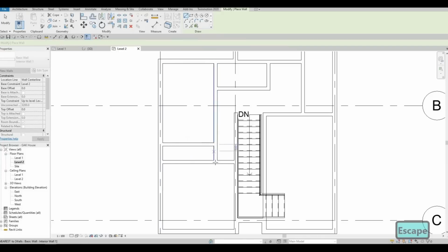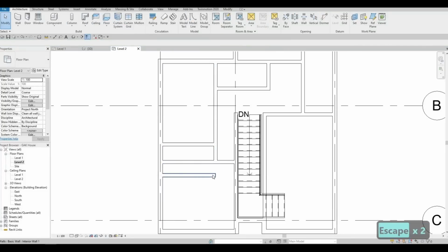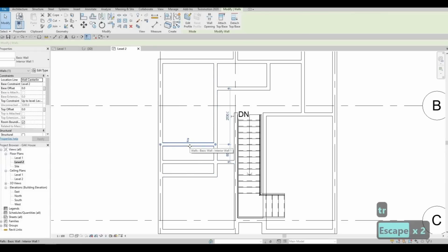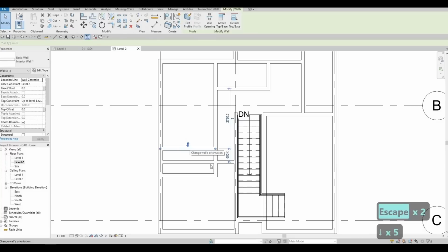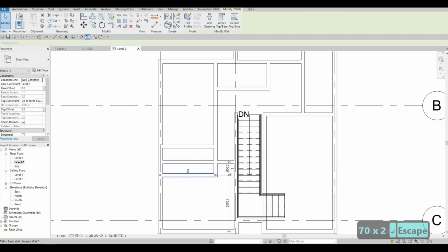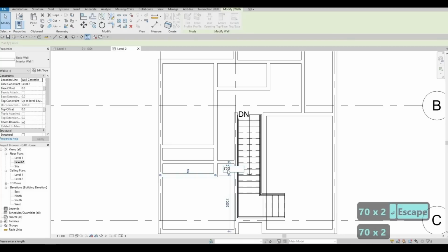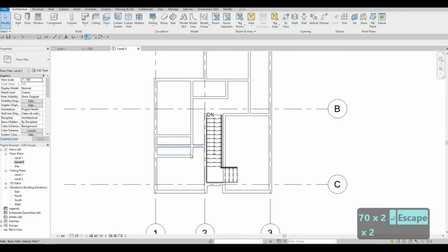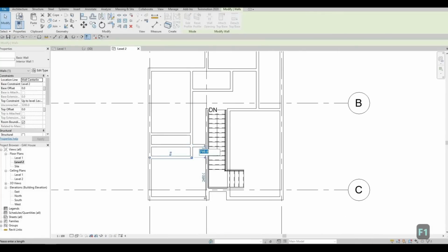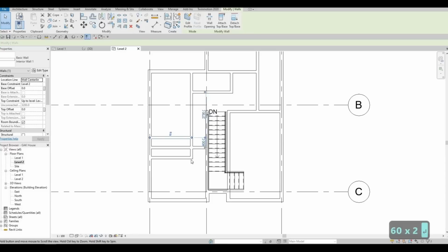So I'm gonna add the closet right here, and I wanna add the closet right here as well. Here, type in TR, click this one and here, so that we can have the closet. The closet around 700 will be enough. 700, 800. I think 600 is good. Yeah, 600. It's too much.